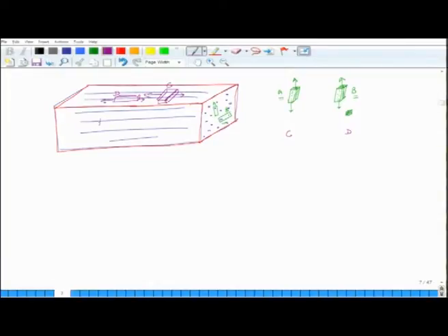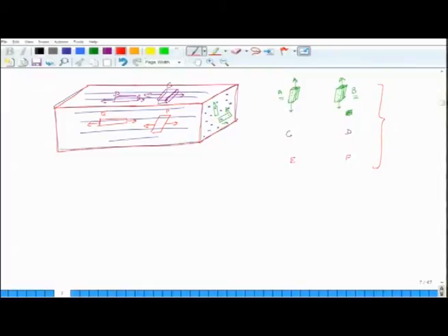So, this is sample C and sample D, and then let us consider another one. This is sample E, and you can test it in tension, and this is sample F, and again you test it in tension. So, you will see that E and F, their properties will also be the same, which means that for this material, if I cut the material with respect to these 3 planes, then within the plane I can keep on rotating the orientation of the sample, and the properties do not change within the plane. So, this material is behaving isotropically, at least in the context of these 3 planes.